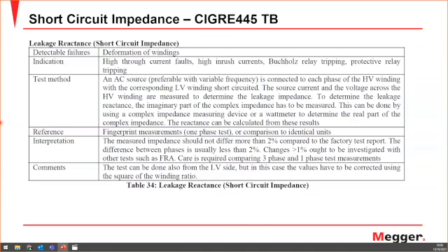There are, of course, some difficulties. It is not mentioned here in the IEC or CIGRE how thick your short circuit should be, how thick is the cable doing the short on the low voltage side. Some people may put very thin cables. We realize this from real experience in the field, so we recommend people to get very, very thick cables for doing these shorts, because you have very high current on the low side.